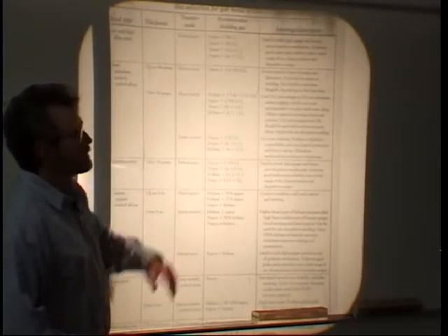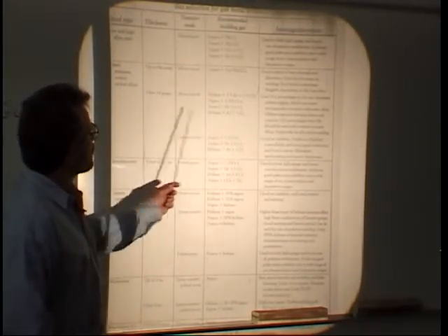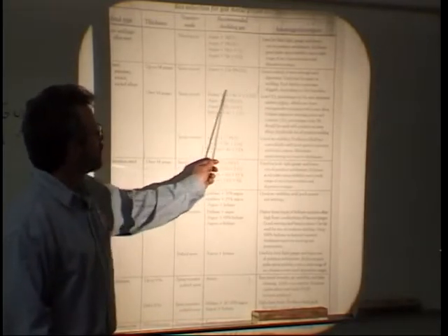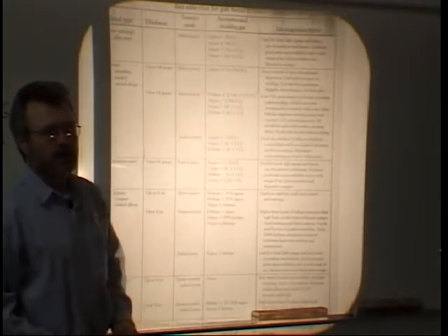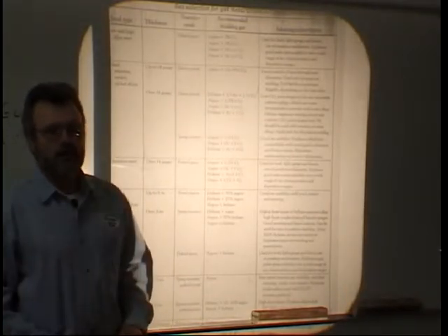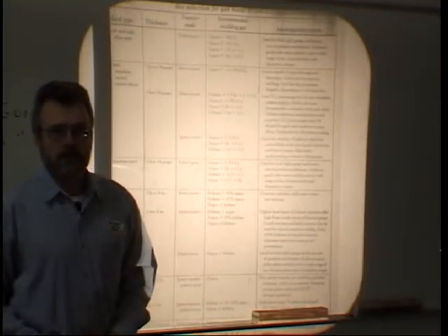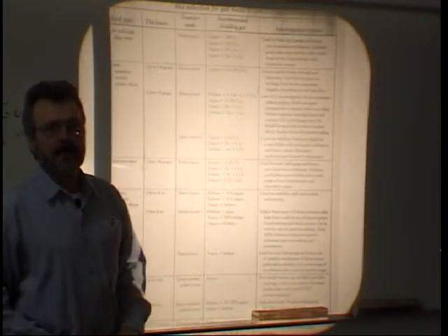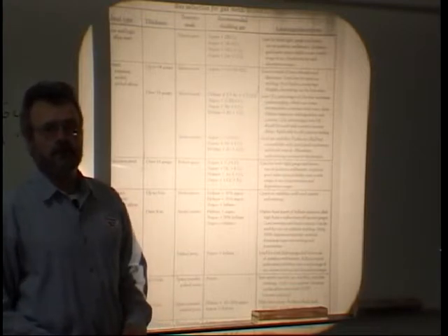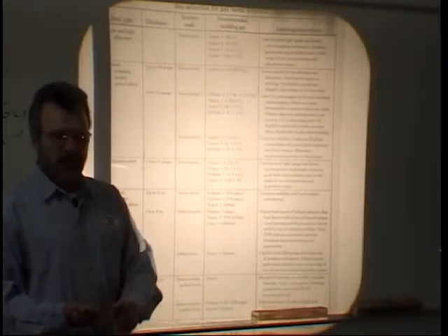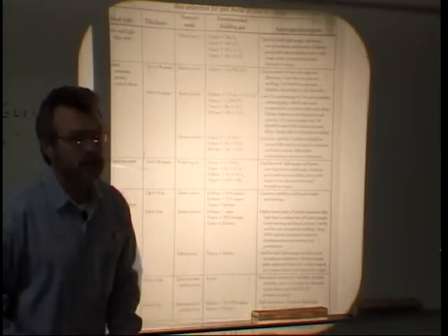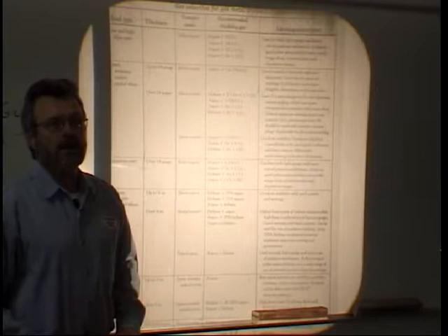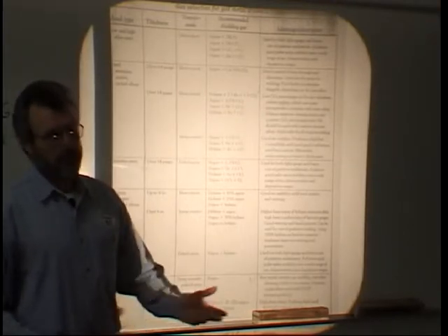And there are many different types of welding procedures that have been qualified using this. And it is called a trimix. I don't know if it's written in your book anywhere, but write that down in your column someplace, trimix. I may ask a question, what's trimix? And you're going to tell me it's a welding gas comprised of 3 different types of individual gases, and that would be helium, argon, CO2. That's a trimix. Or I may ask a question, well, what kind of metal or steel would you weld with a trimix? And you're going to answer stainless steel. Okay?